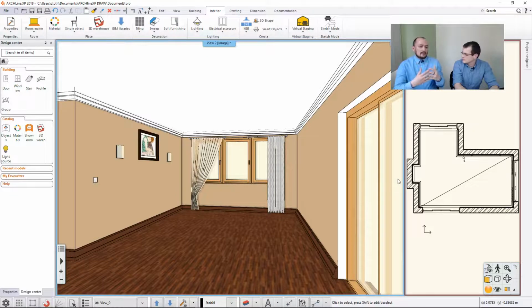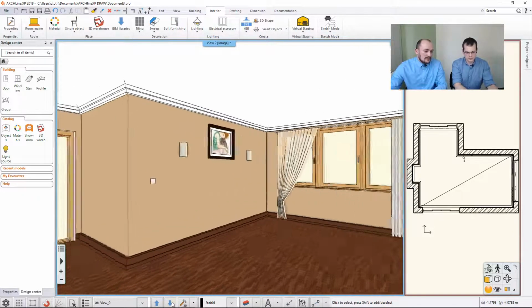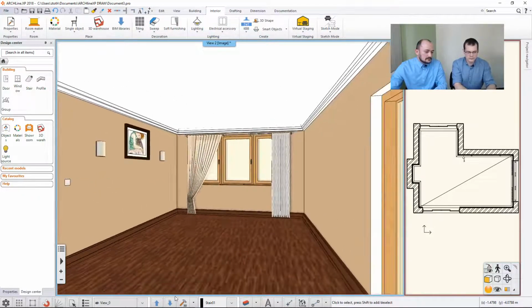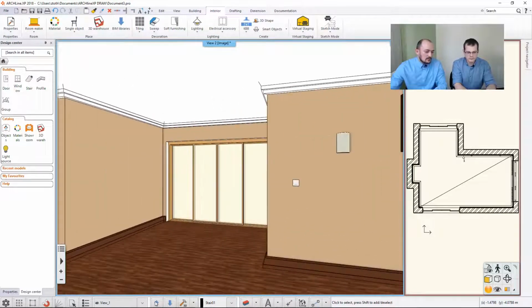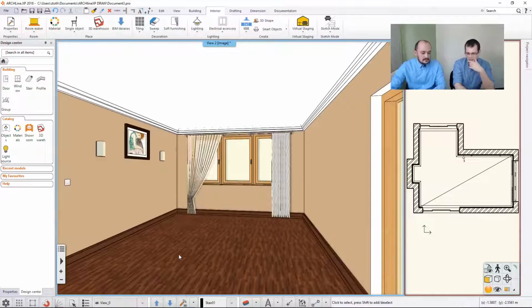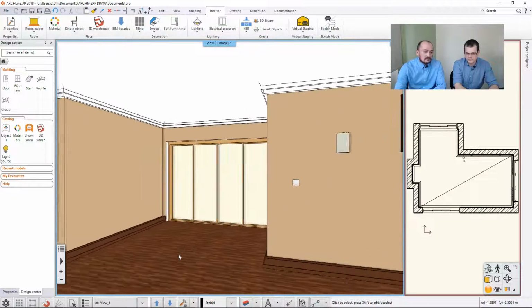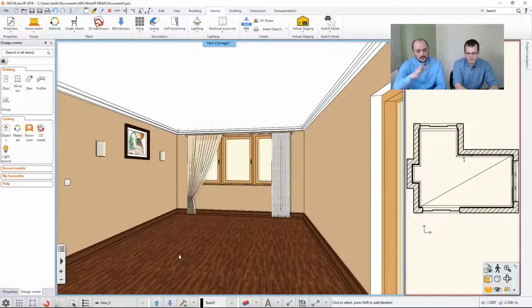So even when I'm working with an intermediate size model, I just quickly set up several views, and I think it's a useful trick to know there is this here. With this one, you can navigate from one view to another. See, I'm just jumping from one view to another. It's easier that way. This is used based on that setting that I already created. I also know that the Page Up, Page Down keys would do the same trick. On your keyboard, you all have a Page Up and a Page Down button, and that's doing the same. Page Up is going to the next, Page Down going to the previous.